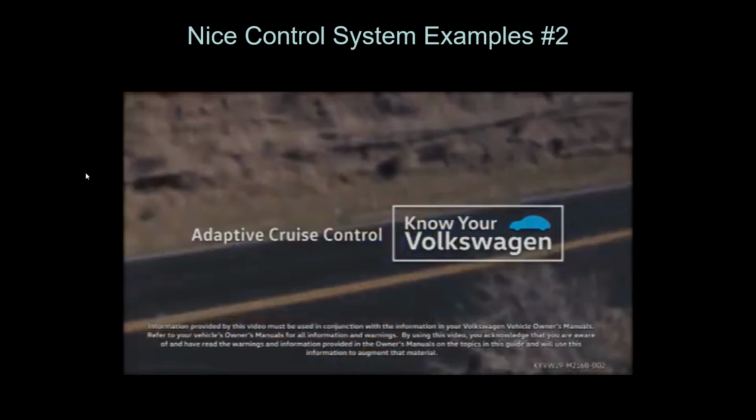But a classical, basic control system allows you to set a cruise speed, and then it will hold that speed. So, for instance, if a vehicle starts going up a hill, it would automatically slow down. So the cruise control system then would accelerate the vehicle, or would give more torque to the engine or to the motor to keep the set speed. If the vehicle is going downhill and starts to accelerate, it would ease back on the torque from the engine or from the motor to slow the vehicle down and try to bring it back to its set speed.